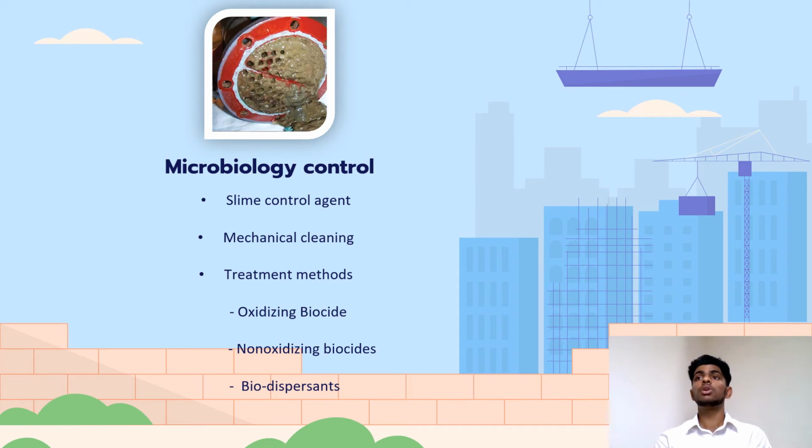They are generally short-fed to achieve a high enough concentration for a long enough period of time to kill the bacteria, algae, or fungi. So the biodispersants do not kill organisms; they loosen microbial deposits, which can be flushed away. They also expose new layers of microbial slime or algae to attack by the biocides.